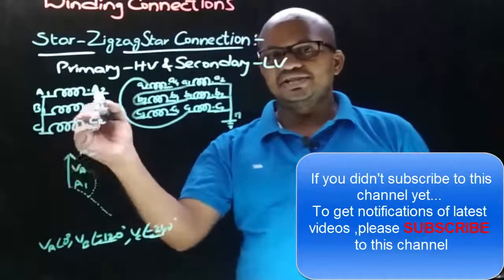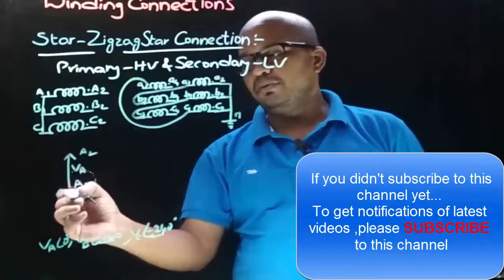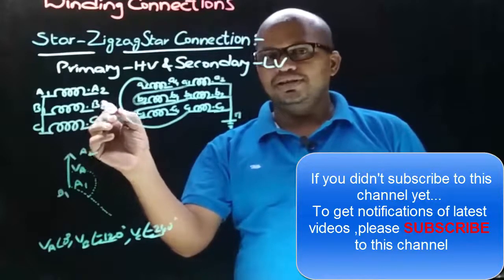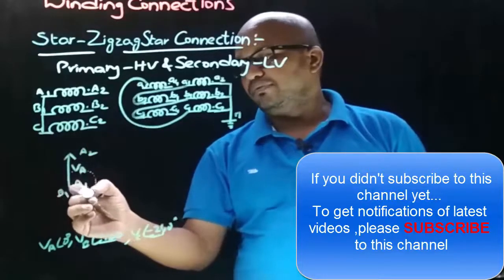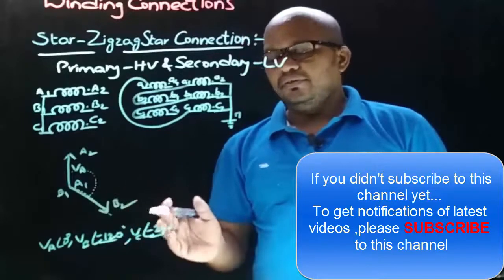And observing the winding connection, to A1 there is a B1 connection, means A1 must have B1, and as the connection is taken from the dot end, that is B2, the arrow will point towards B2. Therefore the VB phasor will be like this. Now we must draw the VC phasor.